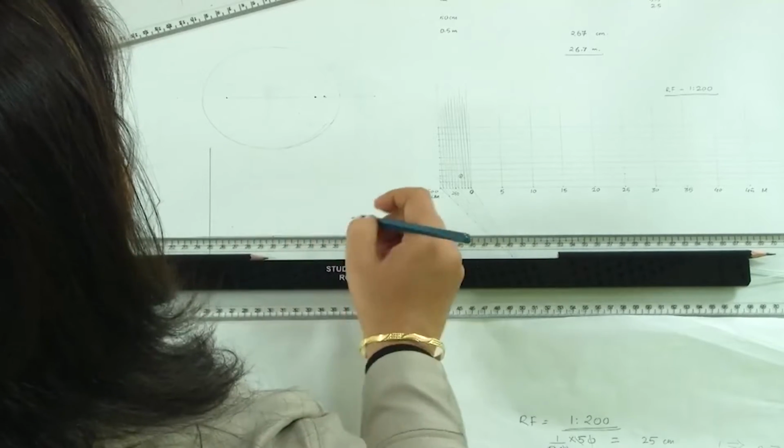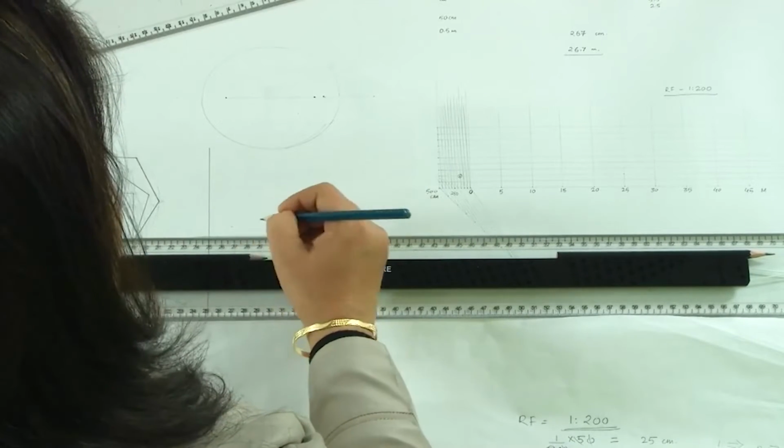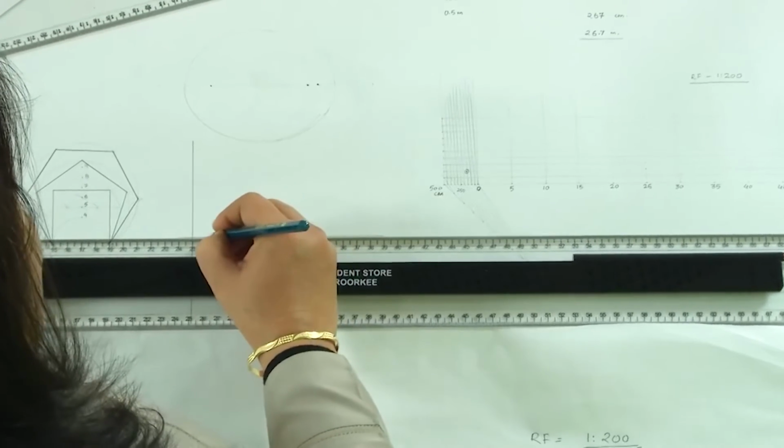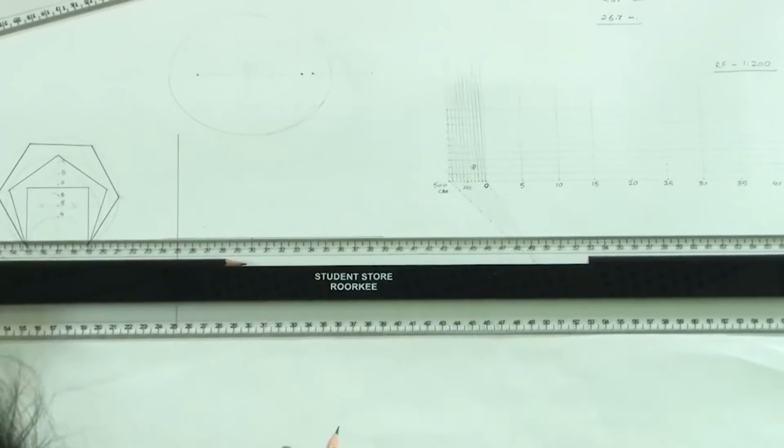So, what we would do, we would divide this line into 5 equal parts. I am dividing this line here, it is only 5 centimeters, so it is easy for us to divide. But if it was some odd number, say 7 centimeters, and then we had to divide it, and the eccentricity was given as 2:3. So, we would still divide it into 5 equal parts.